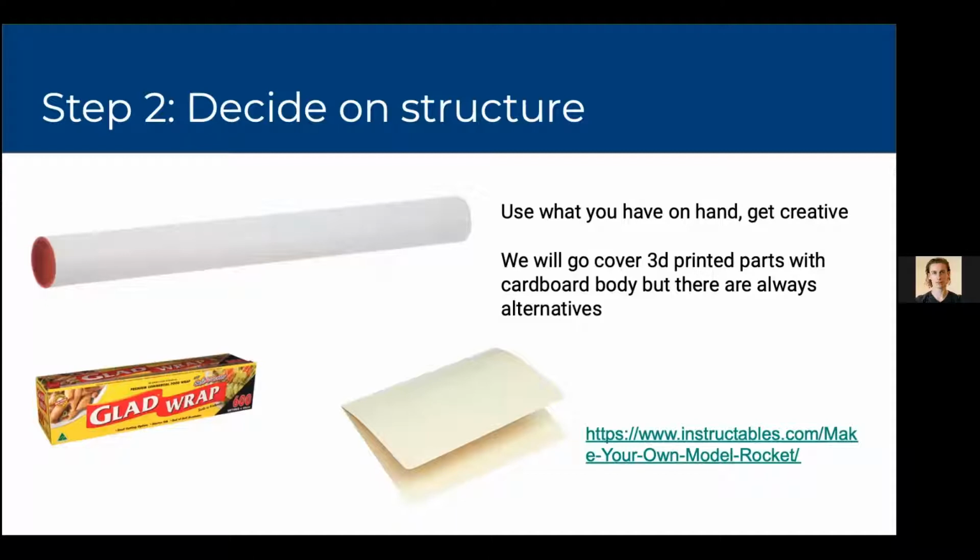So this slide is sort of just to show that you don't actually need fancy 3D printers and exactly sized cardboard tubes, etc. You can get creative, as long as you follow the basic principles of making sure that your rocket is stable, having the center of gravity in front of the center of pressure, all that kind of thing. As long as you have that, sky's the limit. So, next slide, please.